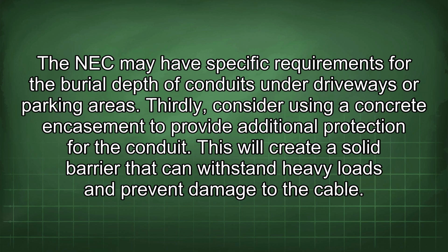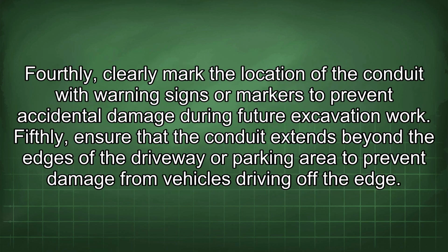Thirdly, consider using a concrete encasement to provide additional protection for the conduit. This will create a solid barrier that can withstand heavy loads and prevent damage to the cable. Fourthly, clearly mark the location of the conduit with warning signs or markers to prevent accidental damage during future excavation work. Fifthly, ensure that the conduit extends beyond the edges of the driveway or parking area to prevent damage from vehicles driving off the edge.